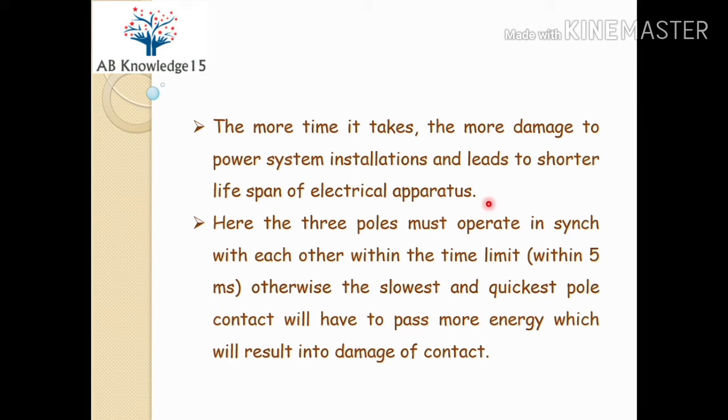So we are talking about that here three poles must operate in sync with each other within the time limit. Otherwise, the slowest contact and the quickest contact will have to pass more energy, which will result into damage of the contact.